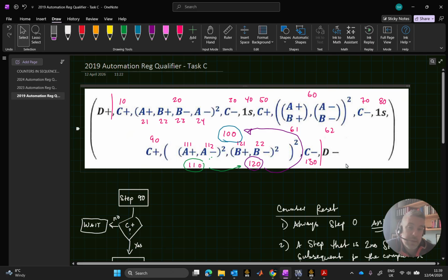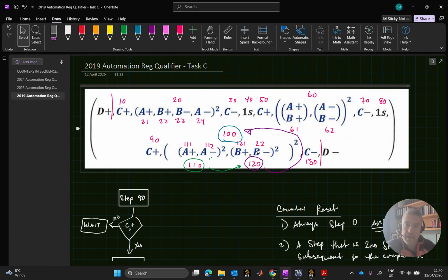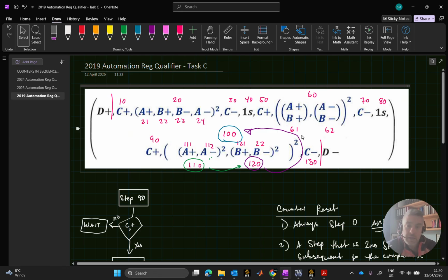Now you can use a lamp actuation, as I said, I think it was in video 1 or video 2 or whatever when we were looking at the counters. It's 9 times out of 10 that it might work, but there is a chance that it won't work because it just actuates too quickly. The reset goes too quickly. The lamp actuates, the output fires too quickly. We're not waiting for an input here. We're waiting for an output to fire in these, and they're instant. So there could be a chance that you reset your counter before it registers itself being done, and then you go back into it and you're stuck in an infinite loop of the counter subsequence executing and it not accumulating counts. That's what I'm trying to avoid.